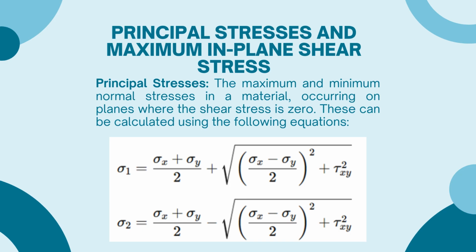Now, let's look at principal stresses and the maximum in-plane shear stress. Principal stresses are the maximum and minimum normal stresses in a material, occurring on planes where the shear stress is zero. These stresses are crucial for understanding the material's potential for failure.